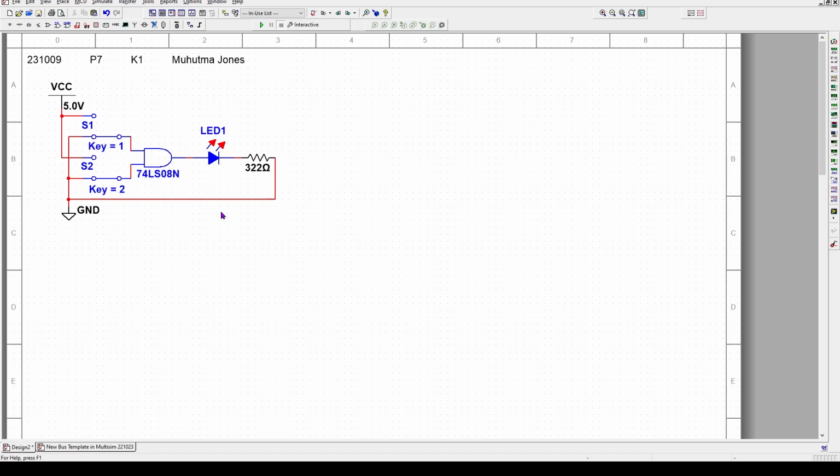Okay. Also, a question my students have with this is, well, if you put a resistor here that drops the voltage for the LED1 down to 2.5, aren't you also dropping the voltage back down to 2.5? And this component, this AND gate, needs 5 volts. So the answer to that is that hidden behind and not showing and implied and assumed is that this AND gate is also powered and grounded behind the scenes.